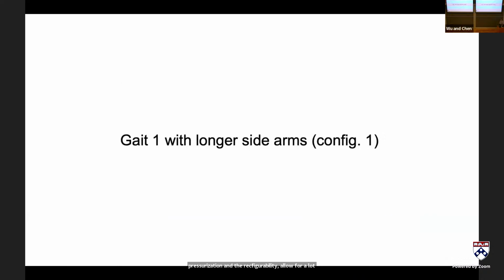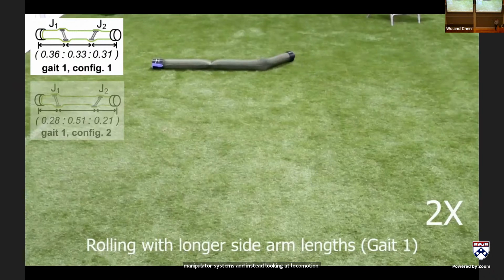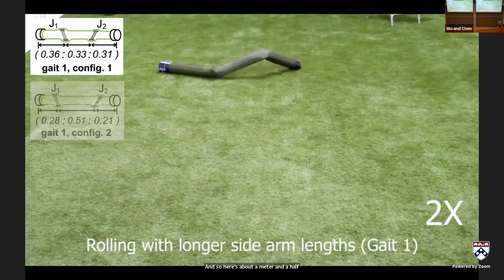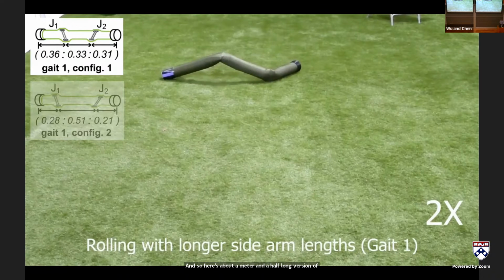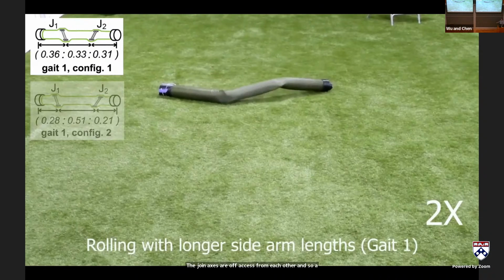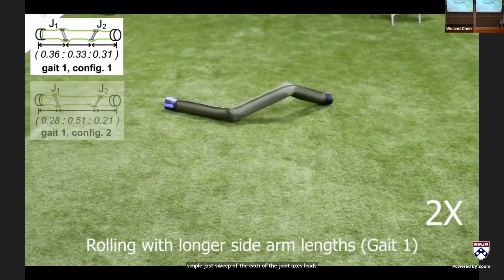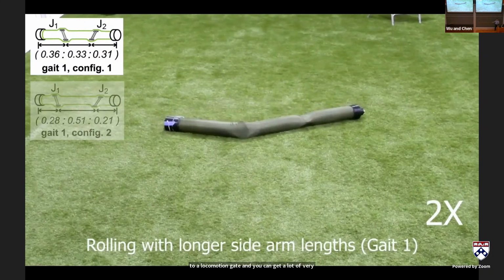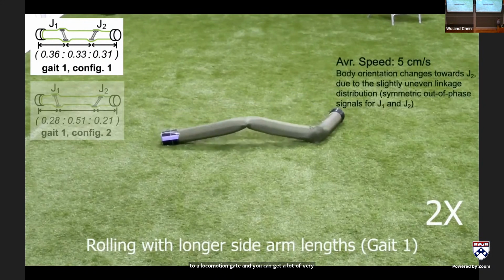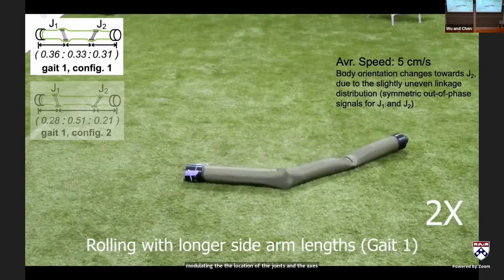One of the ones that we were really interested to explore was actually moving beyond thinking about like manipulator systems and instead looking at locomotion. And so here's about a 1.5 meter long version of this with 2 joints within it. The joint axes are off axis from each other. And so a simple just sweep of each of the joint axes leads to a locomotion gait. And you can get a lot of very interesting locomotion gaits out of this just by modulating the location of the joints and the axes of the joints, which we've studied in a manuscript that's in review right now.